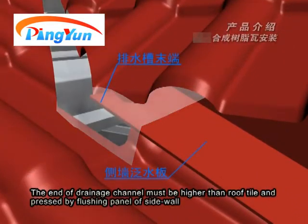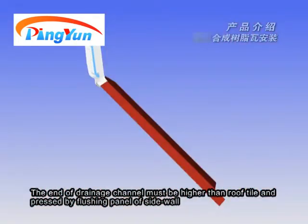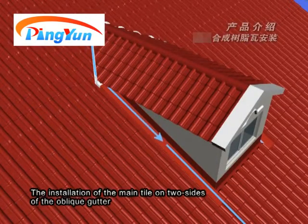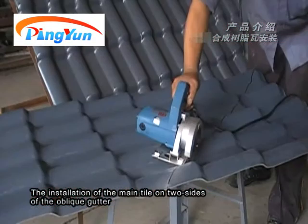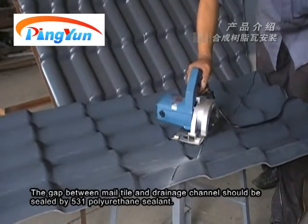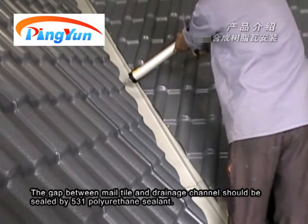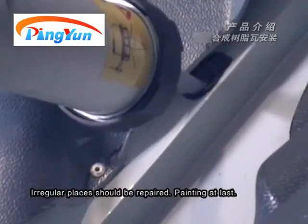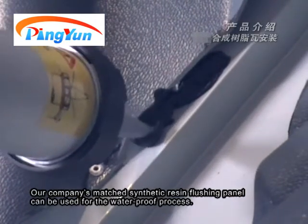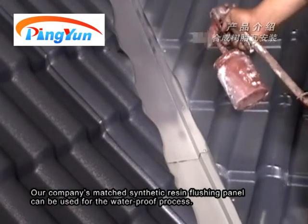The end of the drainage channel must be higher than the roof tile and pressed by the flushing panel of the side wall in order to connect the oblique gutter and flushing panel or eave gutter. The main tile on two sides of the oblique gutter should be cut carefully according to the shape of the drainage channel. The gap between male tile and drainage channel should be sealed by 531 polyurethane sealant. Irregular places should be repaired. Painting at last.